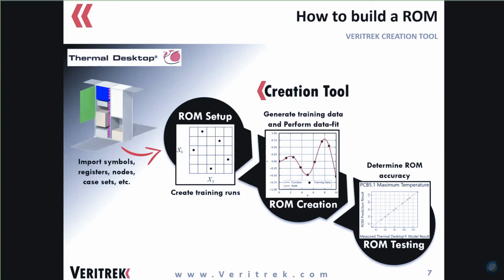Once those are imported into the creation tool, the user is able to select and set up the inputs and outputs that they want for their ROM. Once the user does that, Veritrek takes over in a pretty automated fashion. Veritrek will go ahead and create the necessary training runs for us. It'll generate that training data by performing each of those training runs in Thermal Desktop, and then running that training data through our data fitting algorithm to complete the ROM creation process.